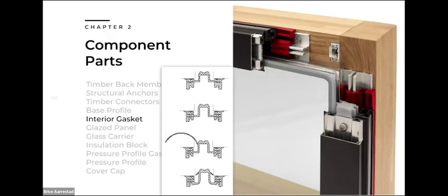That one with the hook there, that would be a sill profile. So that flap is able to wrap, and you're able to use that to flash through the system, and then it would be trimmed in the field to whatever length it needs to be, as far as its length out of the system, flashing out of the system.